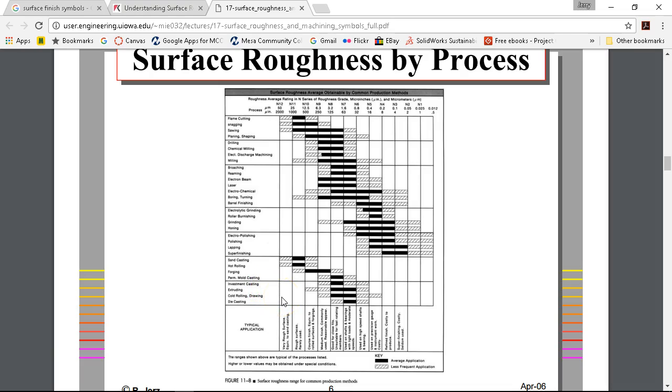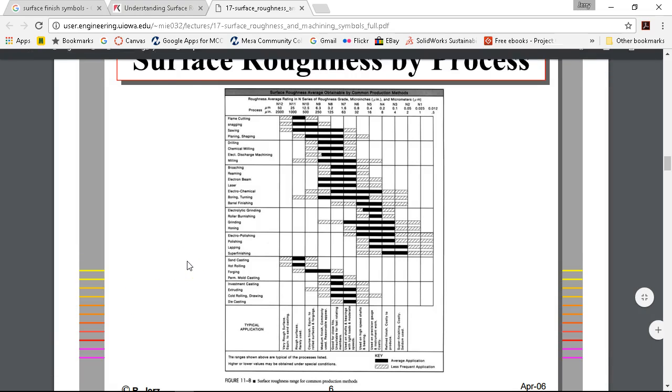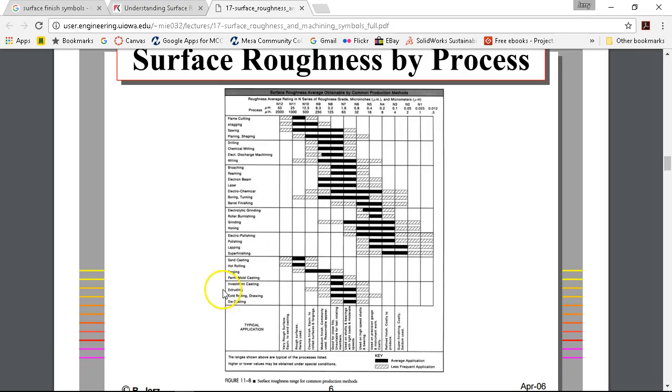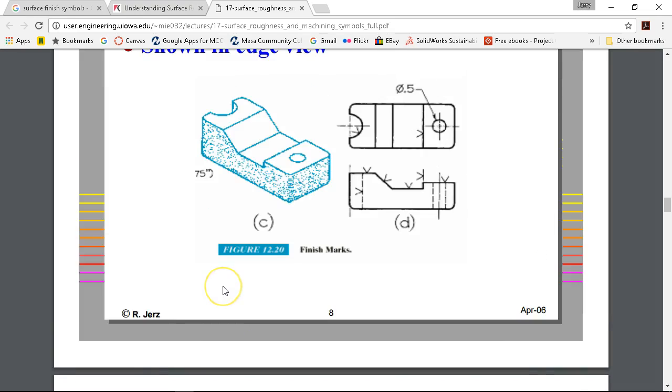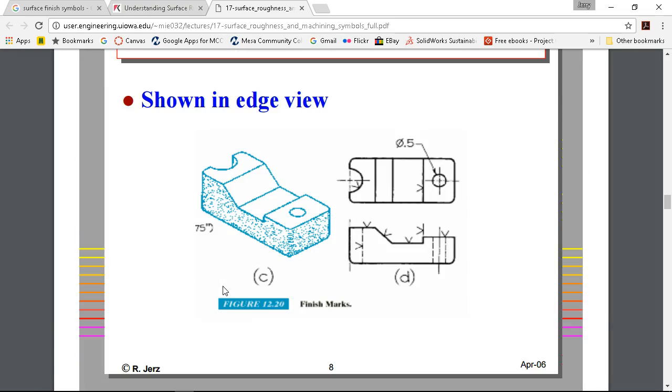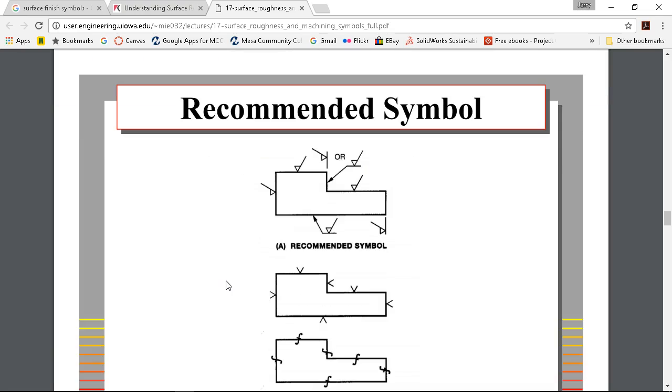Let's see, can't read it too much, but once you get below about 16 micro inches, then you're getting into those special processes, grinding wheels, electroplating, or let's see, what is the other one? Nope, those are still pretty rough. Anyway, electrofinishing, electroplating, going through those extra processes to get those really fine surfaces.